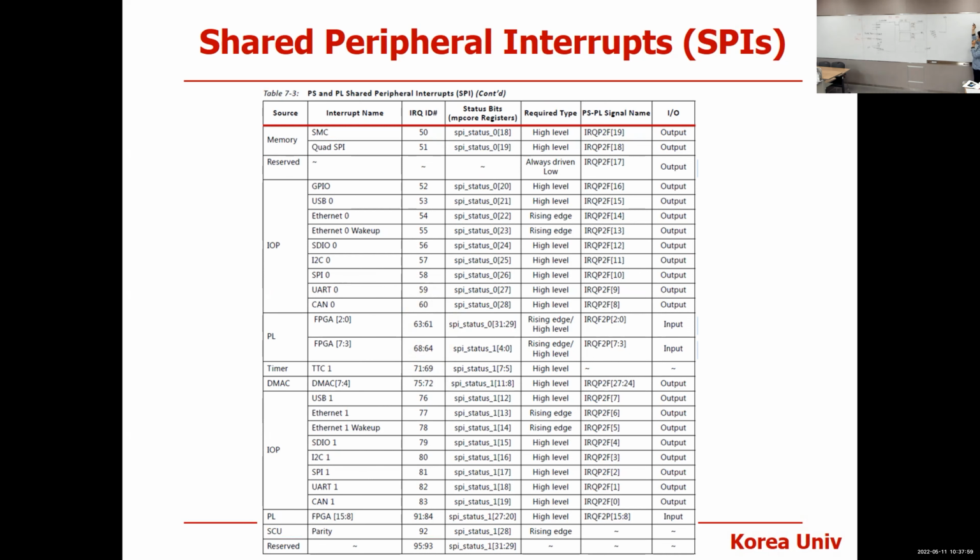Then eventually you want to execute an interrupt service routine. A timer interrupt ISR, and an interrupt service routine for GPIO. There's a separate ISR for USB, and an ISR for I2C. So that is ISR, interrupt service routine. Depending on who generated the interrupt, you want to execute one of these four. Right? That is the goal.